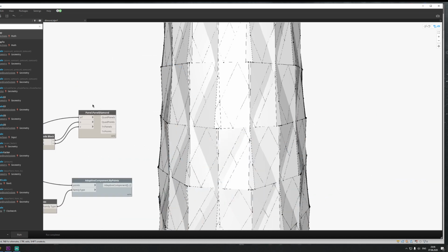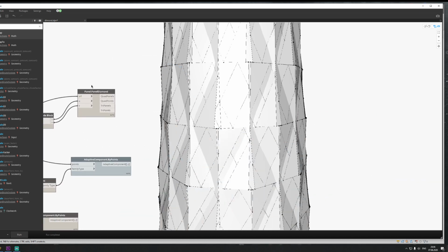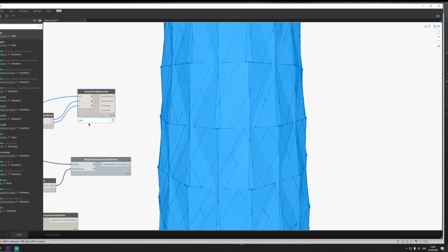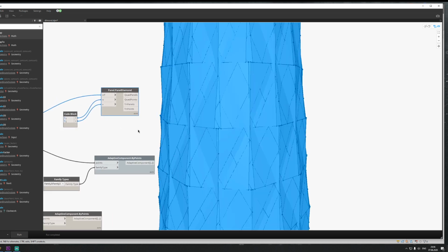So about your AutoCAD file, check your AutoCAD file, because sometimes the problem is inside AutoCAD. What I mean is, in AutoCAD you can also place levels. Check whether it is on the 0 level or not. First check that. Second, when you're loading into the project, the better thing is to use only the link. Only link, I will show you what I mean.